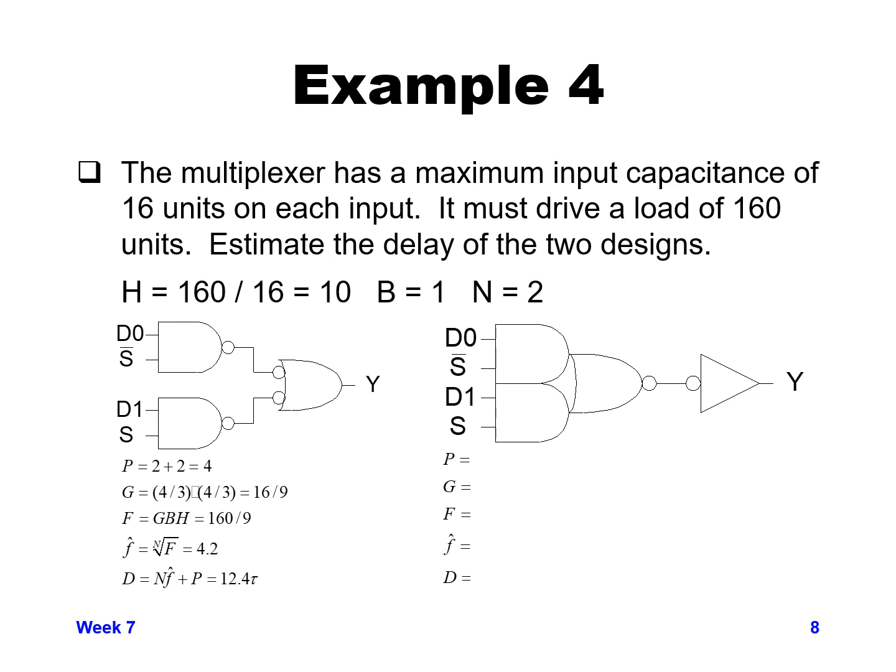Now let's go a little bit more quickly through the next design. Our capital P: the first stage has a parasitic delay of 4, and you can go back in the previous slides in this lecture to see that we calculated that as 4. The inverter has a delay of 1, so the parasitic delay is 4 plus 1 equals 5. For the path logical effort, the first stage is 6 over 3, the second stage is 1, so we just get 6 over 3, or a value of 2.